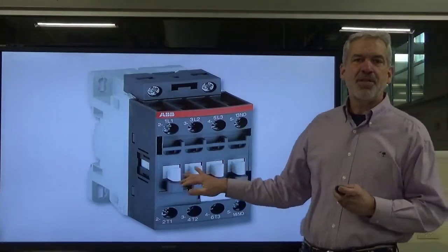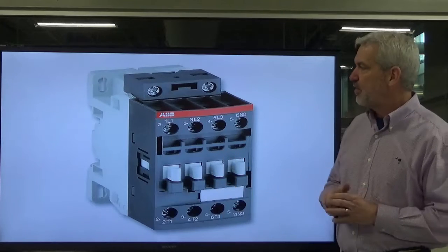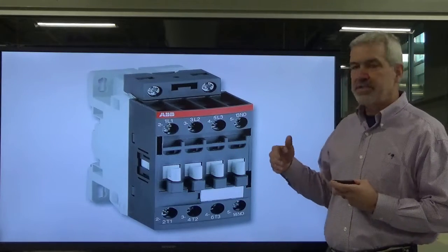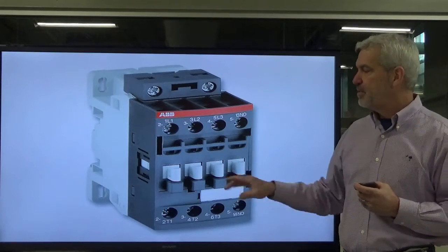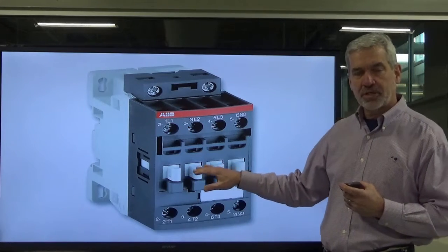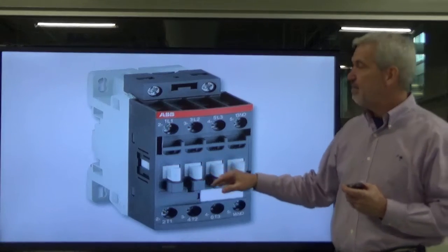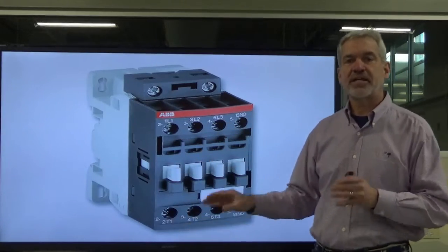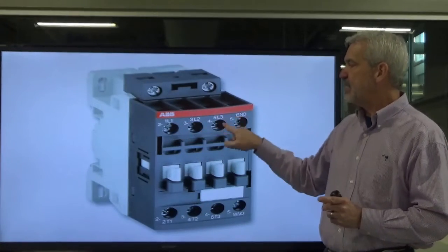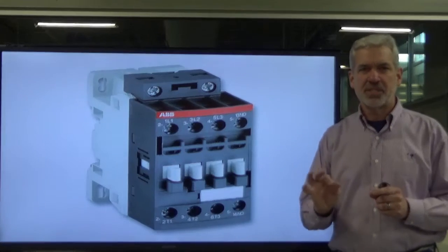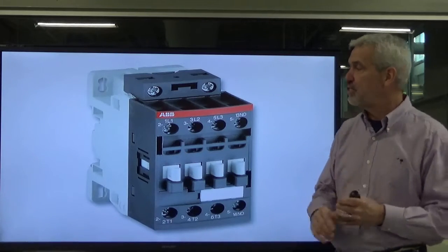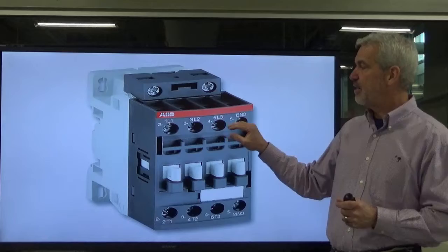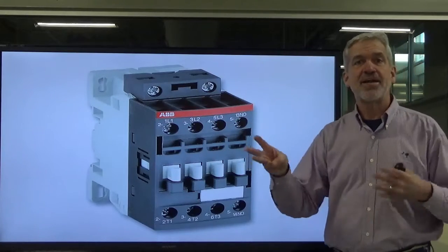And they had an AF30 contactor that when they needed the temperature to start heating up, for the voltage to go into the current to go into the heating element, this contactor will close, and there's 3 lugs, and this is a 3-phase contactor, but they're only using single-phase lines because each one of those elements is just a single-phase element. So it's not a 3-phase system, but they're using this 3-phase contactor because they had 3 elements.